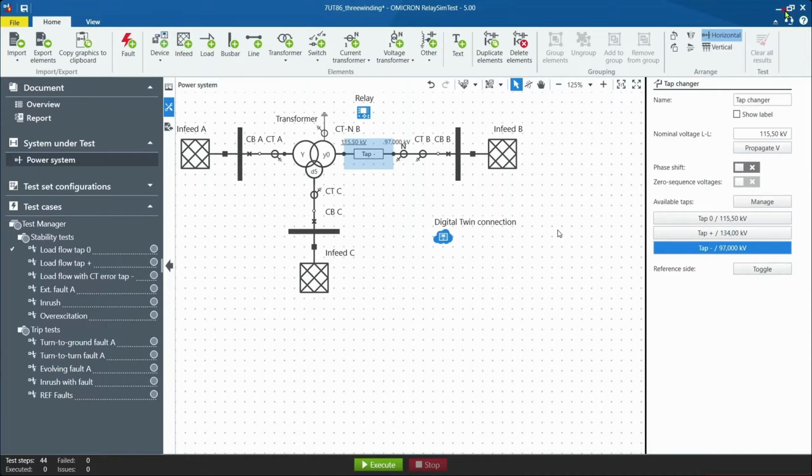Of course, when switching the tap changer, the transformer relay should also not be tripping. Therefore, I have the second state when I change the tap changer to my second position, when no trip should be occurring. Also, when applying a different tap minus, and also with a little CT error, which is available in a realistic behavior, the relay should also not be tripping.